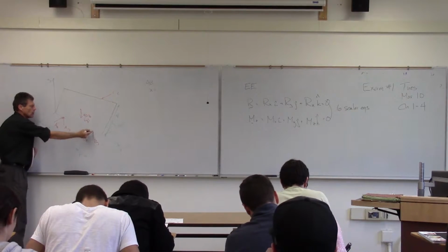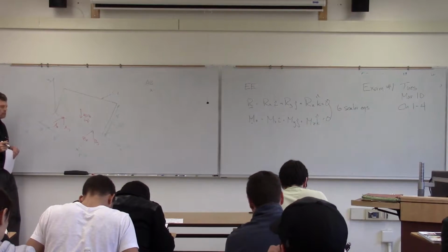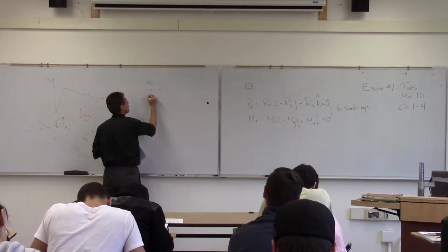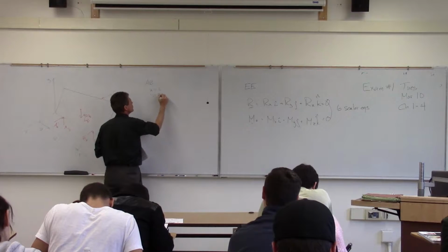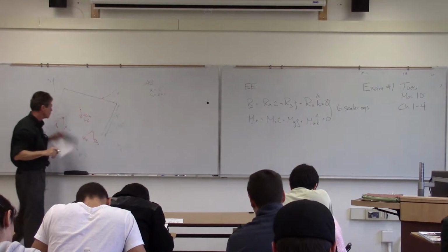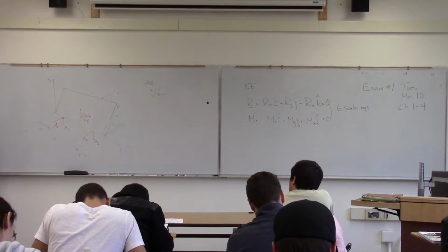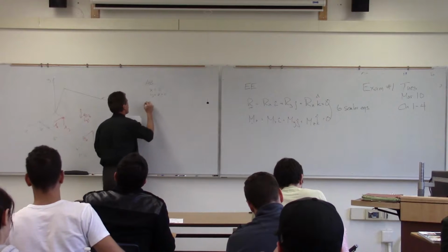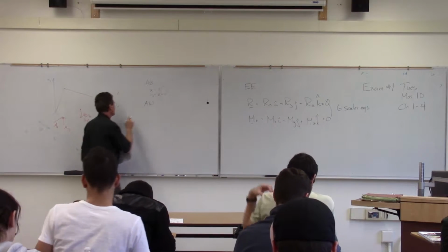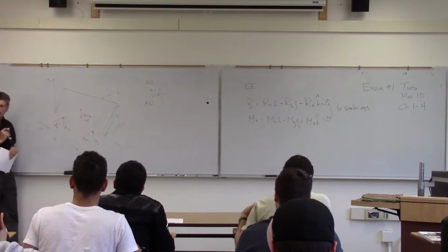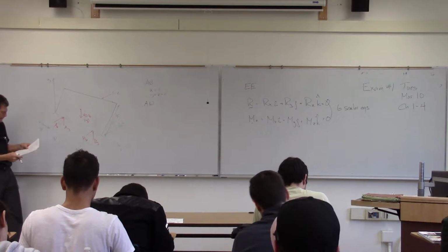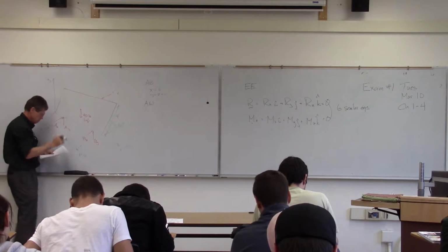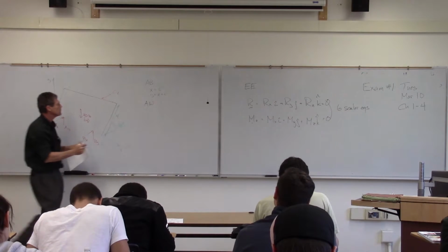So I'm here, and I want to look at the forces there at B. My x component will be 5 feet. Y and z will both be 0. So it's just straight down the x-axis there, pretty straightforward, and that's going to be one of my easier ones. I need to go AW. I need to go to my weight there, my 40-pound weight. So when I think about getting over to that, it's going to be 2 over in the x direction.